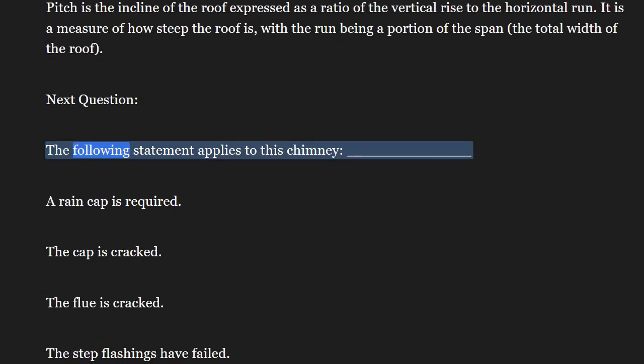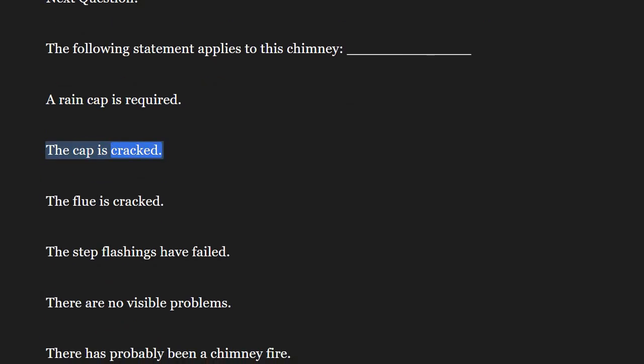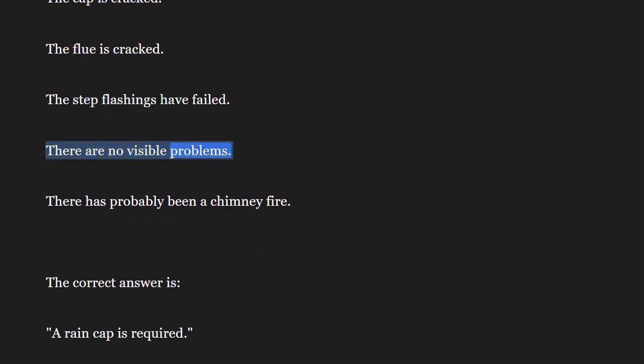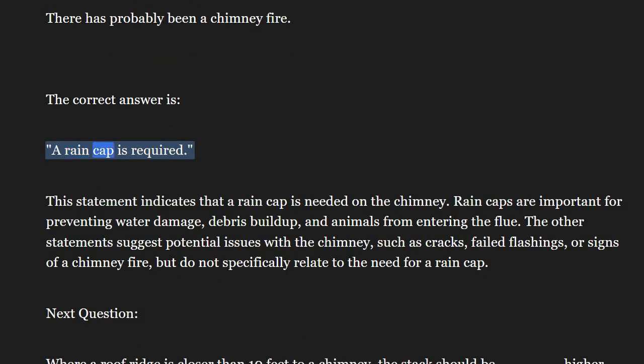Next question. The following statement applies to this chimney. A rain cap is required. The cap is cracked. The flue is cracked. The step flashings have failed. There are no visible problems. There has probably been a chimney fire. The correct answer is a rain cap is required.